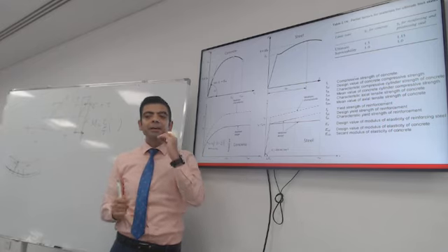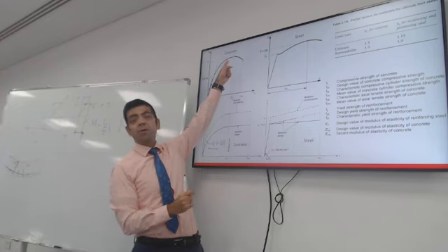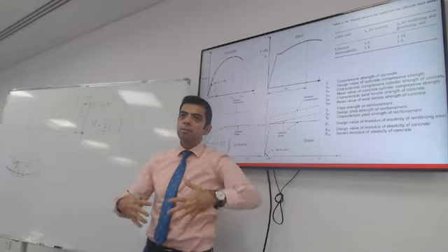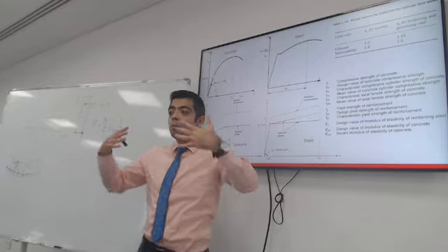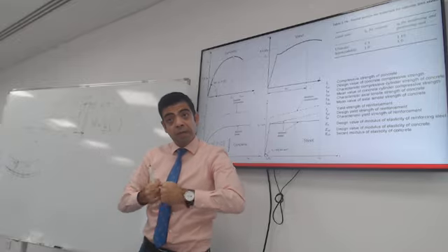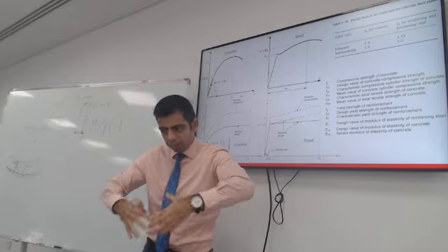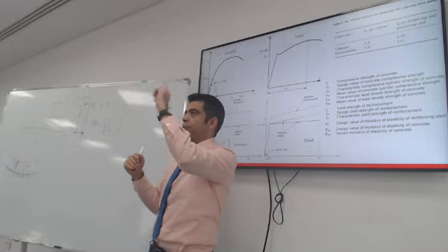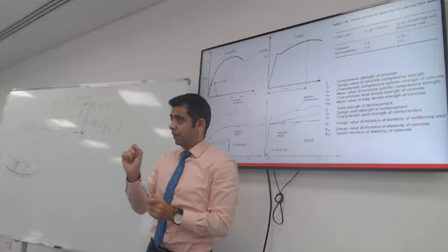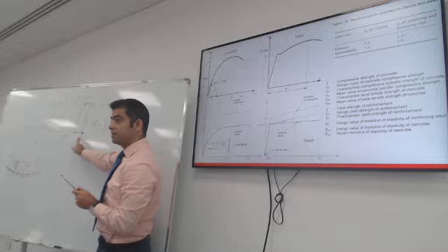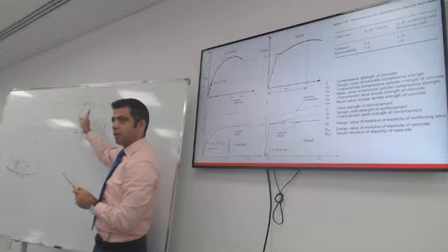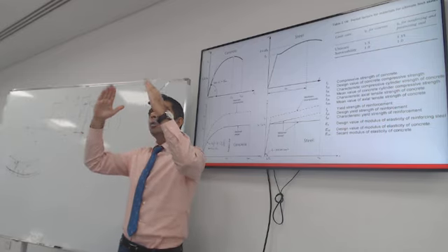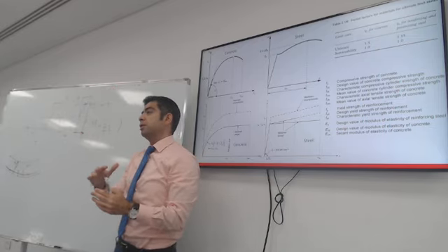You want to limit the strain or the maximum stresses in concrete and allow steel to yield. Because once it yields, the more load you add onto it, it will keep its strength, but will just deform more. So if you overload a floor designed properly to have failure in steel by yielding rather than compression failure, when it reaches the limit, you will find very wide cracks before the floor actually suddenly fails.